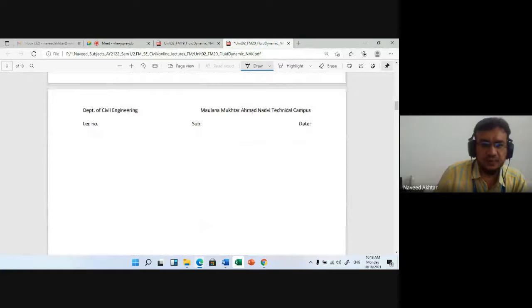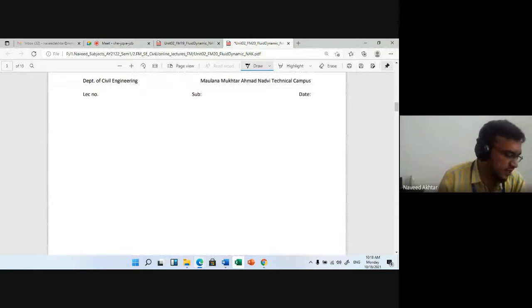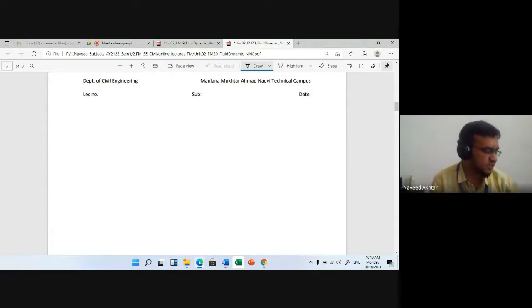So we know that pipe flow problems are very important for engineers who design distribution systems for water supply, waste disposal, and drainage water. These are problems in which control volumes have an extremely large ratio of length to width. Thus, the Bernoulli equation must be modified to account for the energy losses that result from the work done by the tangential stresses.